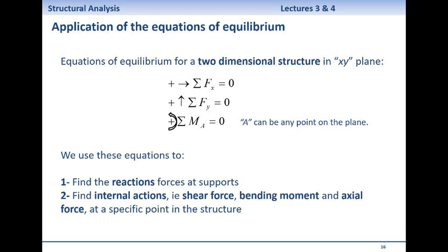There's a particular way that we write this. Because forces are vectors, we need to indicate which direction is positive and which direction is negative, because we need to differentiate between a force that is pushing the structure from left to right and a force that is pushing the structure from right to left. So directions are important, and this is the way we communicate with other engineers.